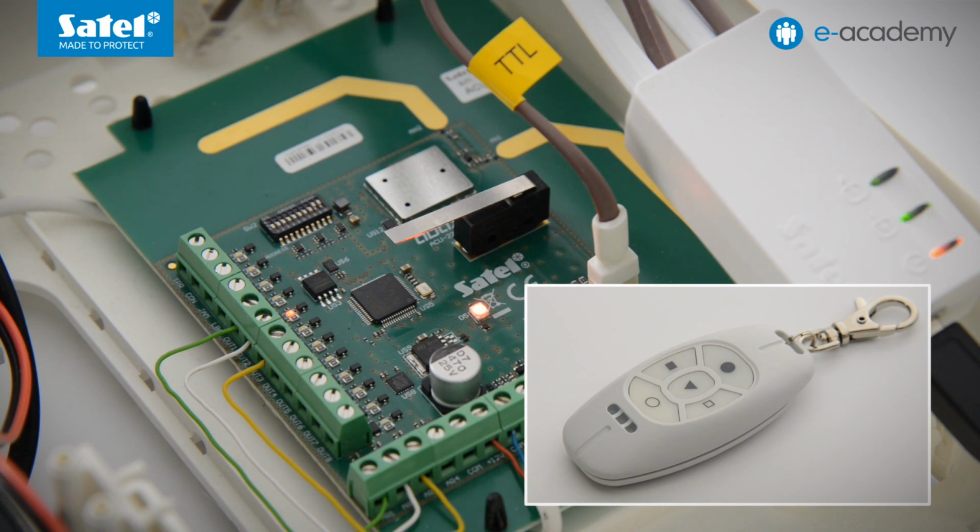The next press of the empty circle button should turn off the out1 output. OK, the key fob has acknowledged audibly it received an answer from the controller, but no LED has come on, which means the inputs are not violated. Now I will show you how to quickly register several key fobs by copying settings, that is, without having to manually assign functions to further buttons and LED indicators.